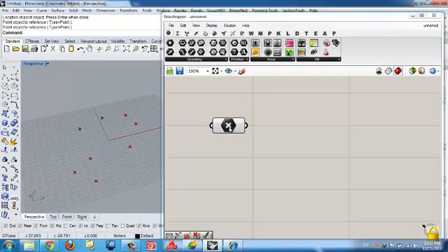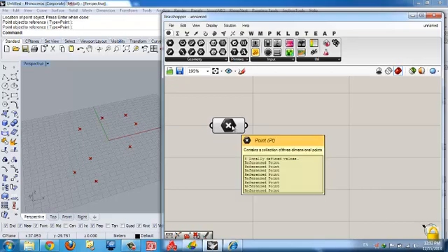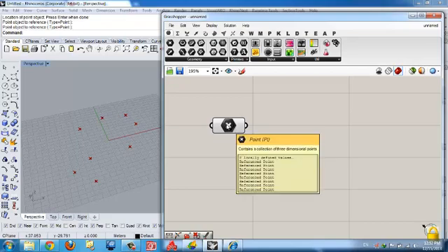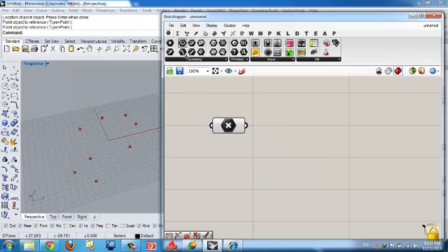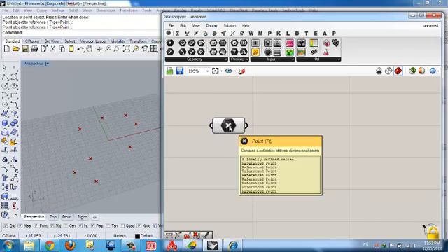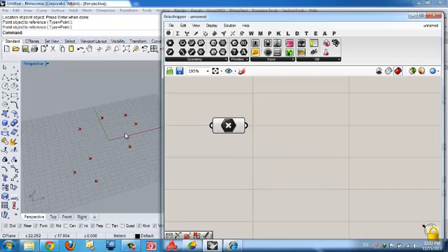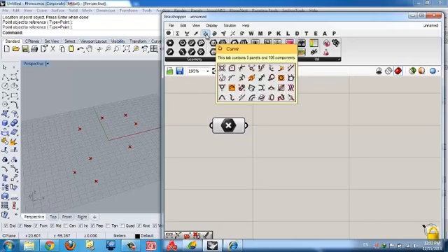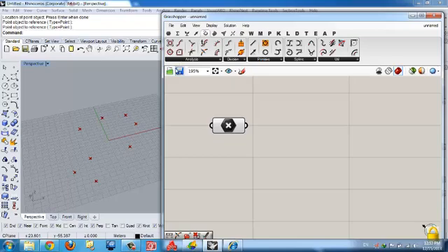This is the import of the points. Okay, so what will happen next? I just want to interpolate these points. If I put the mouse on the points, you can see that I have 8 reference points. That means that the points are in Rhino. So if I just save the Grasshopper, I won't get it next time, except that I have these points right in the place. Okay, so I go for the curve thing, you know, and we want to interpolate.